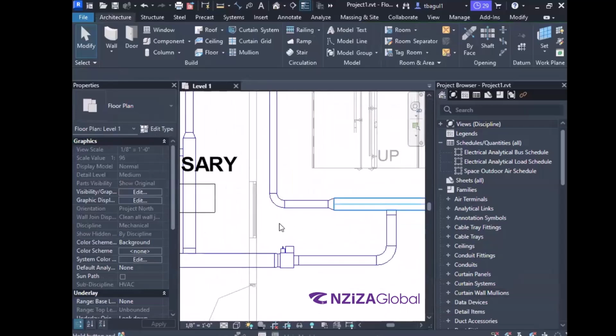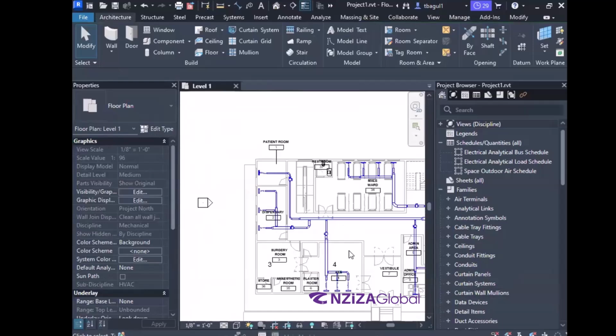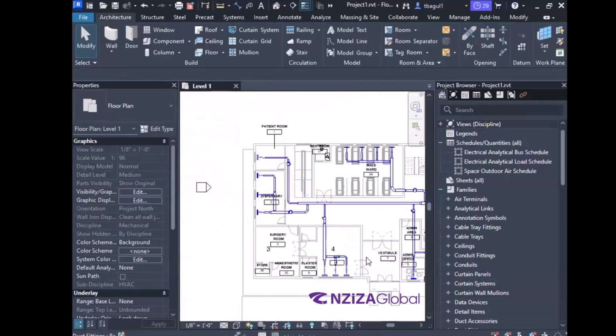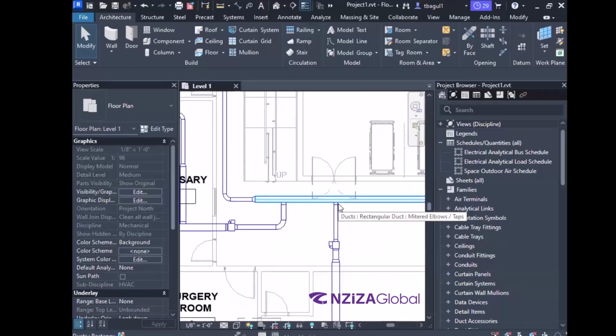The thing is, now if I make it a 10 inch by 8 inch, and then I again put a transition over here, because let's say this particular area over here, the A&E consumes another 500 CFM, right? So at this point, what the duct needs to have is that 285 CFM that is required over here, plus the 500 CFM.